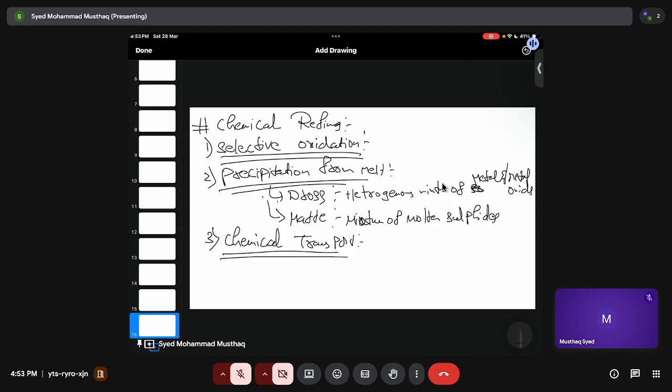So to form the volatile things, you need to react the impurities with certain metals or gas phases such that they convert into the volatile gas phase. For example, you do the carbonyl process in refining nickel. Nickel reacts with carbon monoxide to give nickel carbonyl, and that can again be decomposed to get nickel.